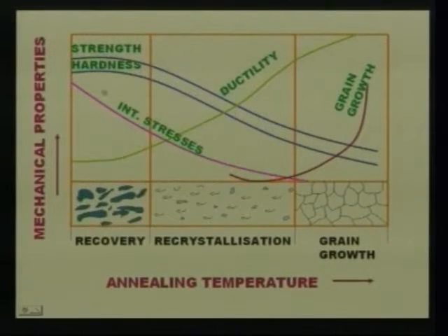You see in recovery the strength and hardness are high, whereas the strength and hardness slowly decrease in recrystallization and also in grain growth, whereas internal stresses are high in recovery, slowly decreasing in recrystallization and grain growth. And ductility in recovery is low, but slowly it is increasing in recrystallization and also in grain growth.